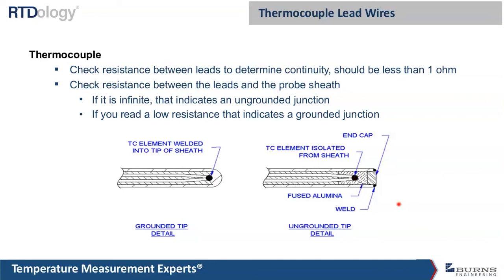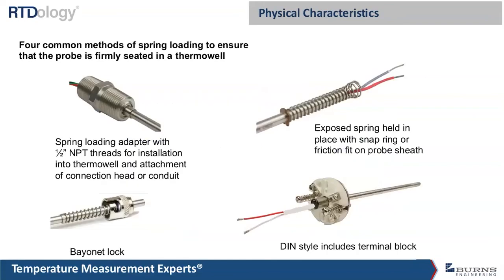That's real important to know when you're trying to identify a thermocouple for replacement. So the physical characteristics of the probes, for example the ones that install into a Thermowell, are going to have some kind of spring loading mechanism on them, and that needs to be identified.